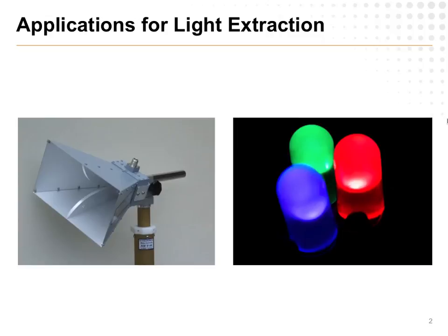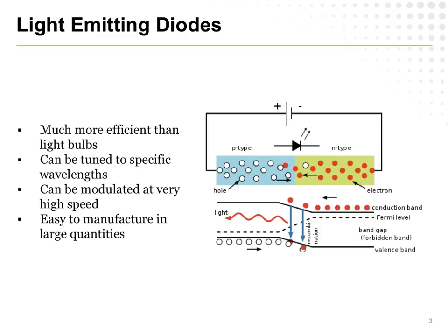There are limitations, of course, because a smaller little die doesn't necessarily mean you can get as much brightness or much total radiated power out of the thing. So, if I had twice the area, I would be emitting twice the photons, and it would look twice as bright in principle. But that's a whole other discussion on how to make these things bright enough to fill a room. The long story short is we really like LEDs. They're pretty cheap, they're straightforward to manufacture, they modulate, they're efficient. There's all sorts of good things about LEDs.